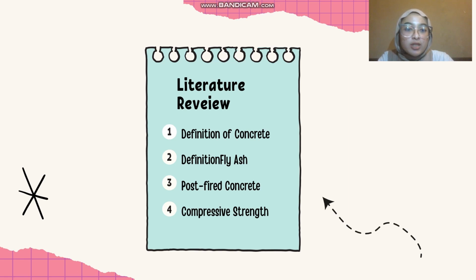The compressive strength value of concrete is known by carrying out tests after the age of 3, 7, 21, and 28 days, by loading with compressive force until it reaches the maximum load.